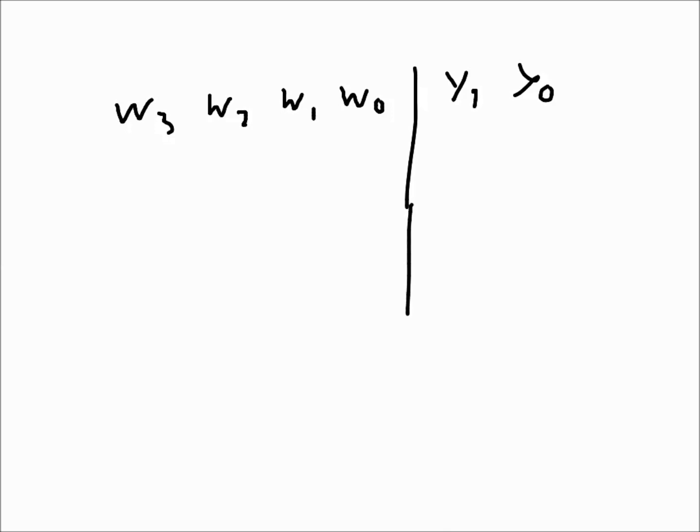So basically what happens here is, let's say we have 4 inputs here. I will talk about the 4 to 2 binary encoder. This is mainly used to reduce the number of bits to convey information. Fewer bits are needed if this encoding is done. So in here only one of the inputs can be active, or if it is active high, we are assuming, only one of the inputs can be 1.